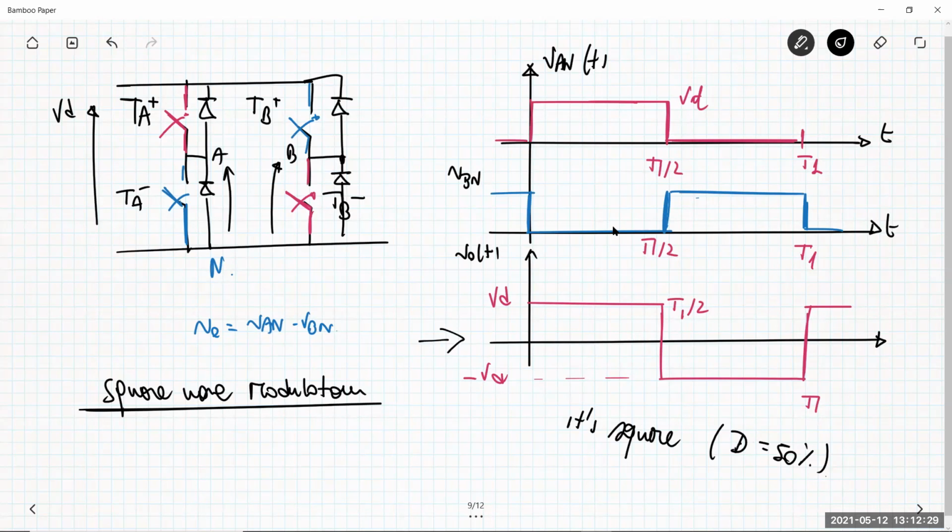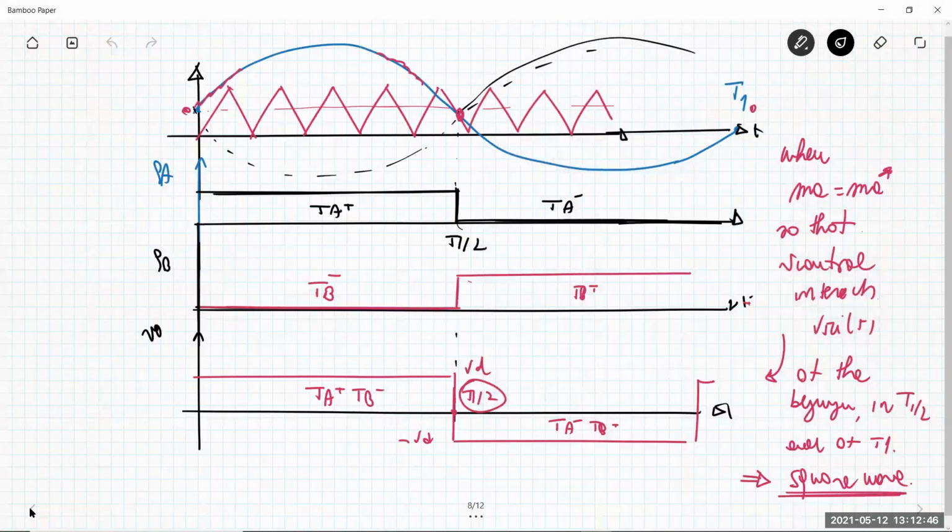So basically this is not obtained by using the pulse width modulator, in which you have the triangular waveform and the control voltage, as I explained to you when we talked about the pulse width modulator. Okay, so I derive it in this way. My derivation here is a purely theoretical derivation. I start from a pulse width modulation with a modulator in which you have a triangular waveform and a control voltage, which is a sine wave. Then I move step by step, using the same approach, to a situation in which this kind of modulator is no more helpful.